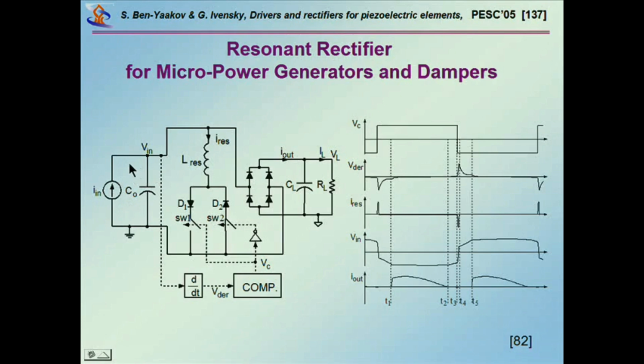And as I've showed you in the introductory part, there is a problem here. The problem is that part of this current is circulating through the output capacitance, and it's getting lost. So there is only that much power you can get with just loading it.